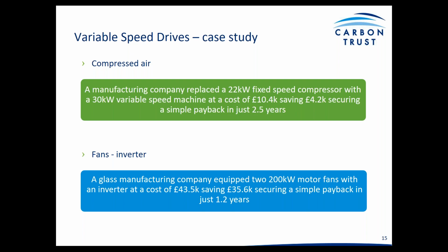Obviously, the benefit of applying a variable speed compressor was that the demand was not constant, so a variable speed drive machine allows the client to adjust the air that's produced by the compressor depending on the demand, the industrial demand of the site.